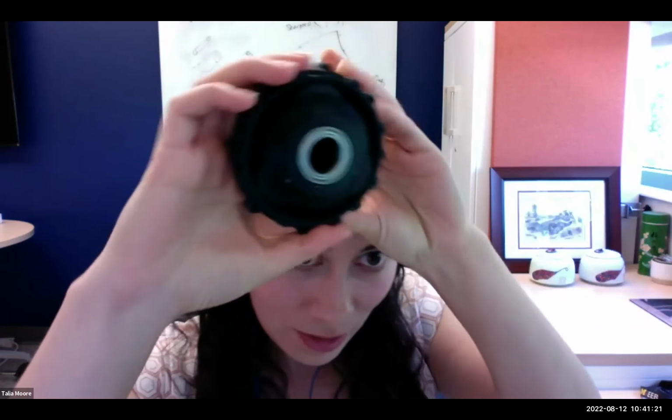I've told you that the surface finish can be poor, and that the machine makes weak and brittle parts. But one of the things that my students have done recently, and I don't know if I have enough light to show you this, there we go, is they've made a fully working 3D printed gearbox, and it's strong enough to run a quadrupedal robot. The way we've done that is by cleverly orienting the print in the Z direction so that we don't have a lot of stress to break apart the layers.